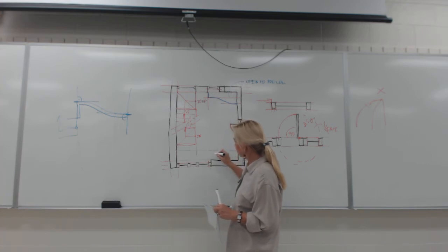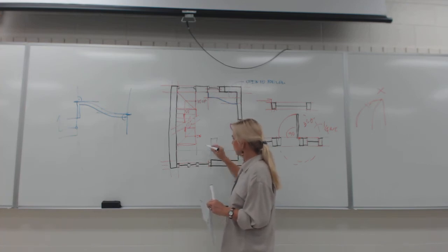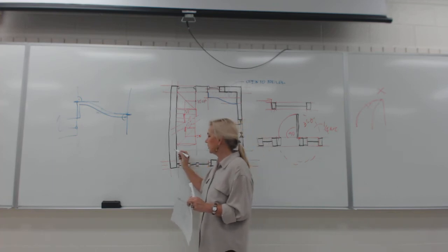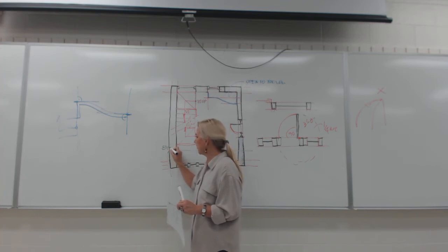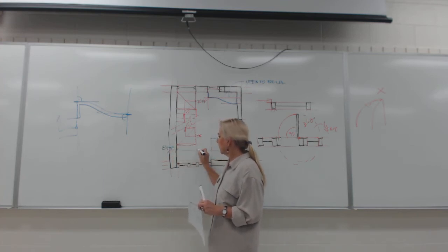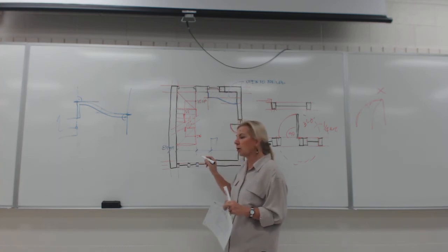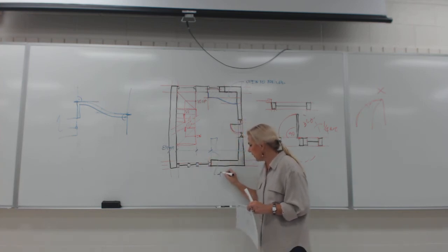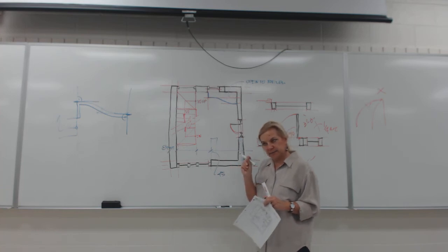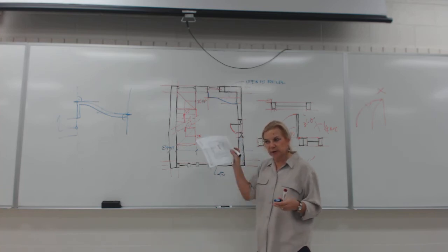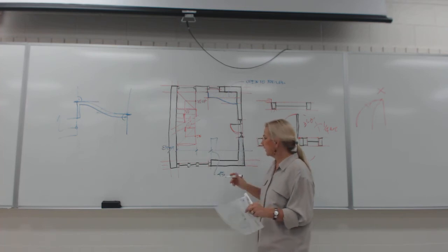You would dimension important features of the kitchen, walls, of the inside in a string. Only once you could show that this is 8 inches, and you could say typical. Then you would show ticks, and ticks are on 45, medium weight line, and they're tiny. They're very, very small. You can see how they look here and copy them.